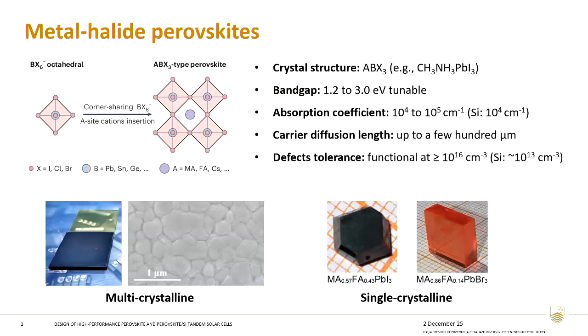With this possibility of varieties of elements in all the different positions, there is also a large family of perovskite materials that has been tested and proven to have good performance in PV applications, including some other optoelectronic devices. Because of this, the perovskite group of materials also has the advantage of flexible tunability in a large bandgap range, down to 1.2 eV and up to 3.0 eV.